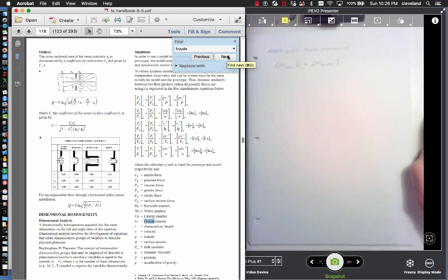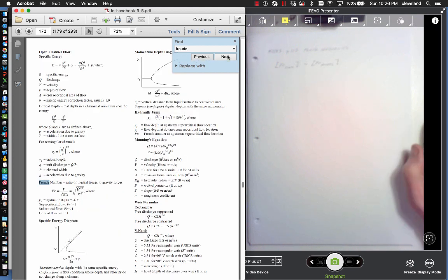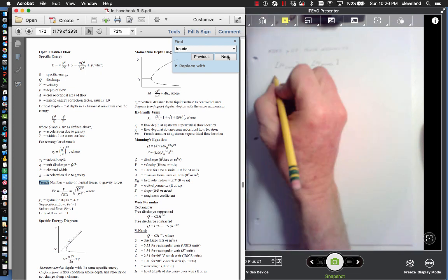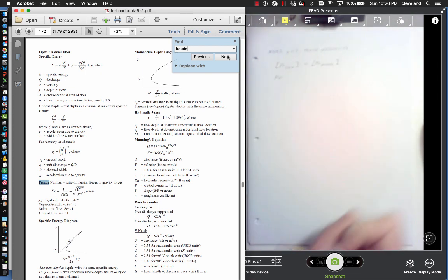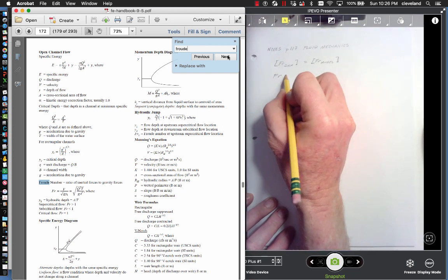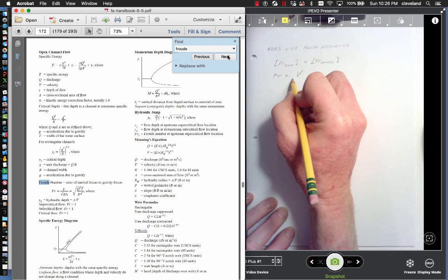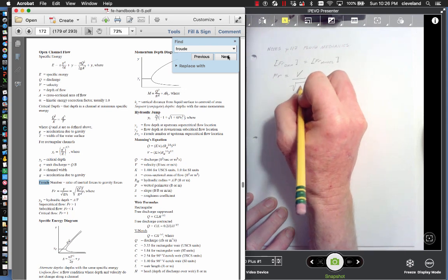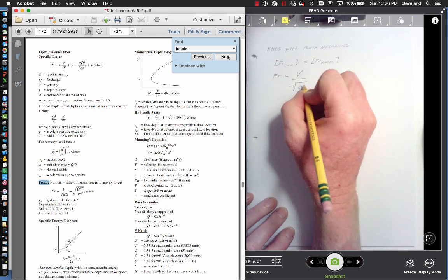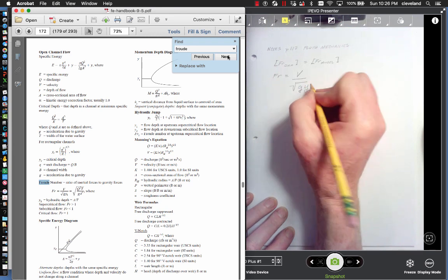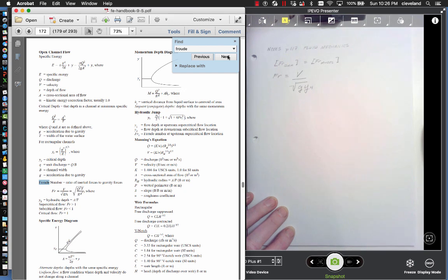Froude number FR. And we now have that the Froude number, by definition, autofocus wasn't focused. So Froude number by definition is velocity over square root of g y sub h. And now we have what we need.